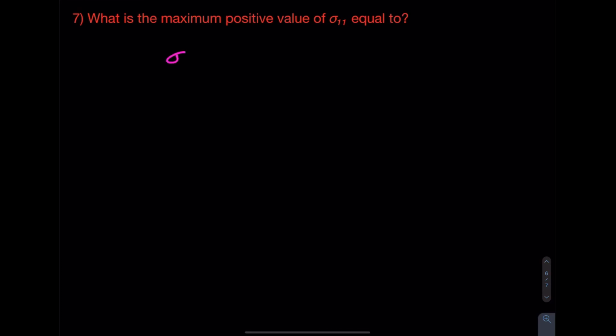So we know that sigma 1,1 in general form is equal to negative M times x2, all divided by the moment of inertia I. Now, one thing I'm going to do, and this will just make my life a little bit simpler and take away a lot of questions from you guys, I'm just going to say this is equal to M times x2 all divided by I. And you're saying, Clayton, what are you doing with that negative?